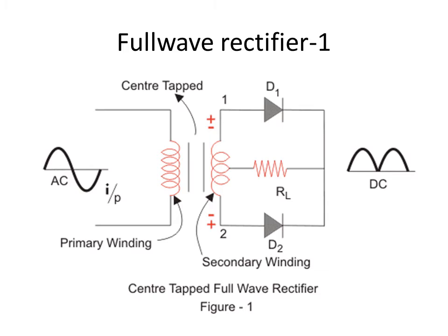So over the years, I have seen some students drawing this circuit. If I don't show them the circuit, and if I ask them to modify the half wave rectifier and draw the circuit of a full wave rectifier, they draw these two diodes like this, and it is correct. But then when they draw the load resistance, they will just connect it in between the two negative end regions of the diode, right?